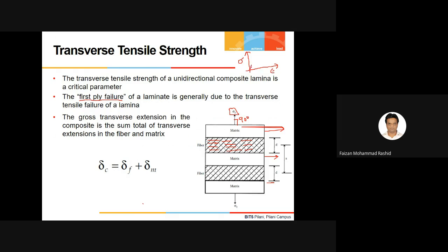You get a straight line, okay, and then you reach up to yield point, and then some deviation will start. Non-linearity will come. This is called yield strength. In composite material, a similar analogy they have made, and they have told that you have linearity, and the moment you have some non-linearity, not very high, okay, some non-linearity, that is called the point of first ply failure.